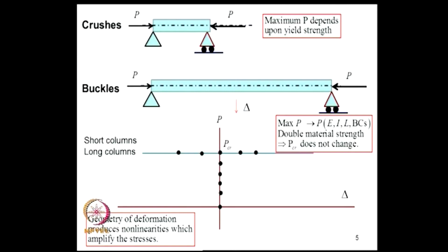Okay. So, suppose we do a kind of a conceptual experiment. We will apply the load P in increments. Suppose we start with 0 and look at the transverse displacement of this beam. We will start with 0, so delta is 0. Now, we will increment P, and after P is incremented, we will pluck this beam and allow it to move. So, assume that it oscillates and assume that this beam has damping in it, it will undergo a free vibration and it will settle down.